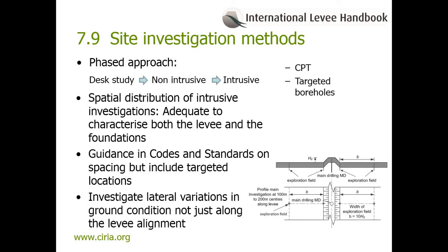Intrusive investigations should be seen as part of a phased investigation, broadly starting with the desk study, moving on to non-intrusive geophysics, and then intrusive. The main intrusive investigation phase may be divided into subphases. For example, intrusive investigation may commence with a series of frequent or closely spaced, fast and relatively cheap CPT soundings.